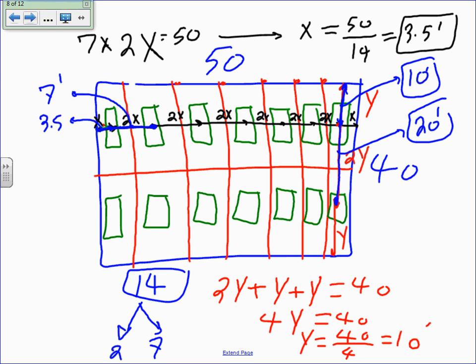So most likely, if I have a grid exactly like this, so 3.5, this is 4, I need a 3.5, so most likely my first fixture, because I can't, is going to be right in this area here. Okay, any question guys about this? Then what's the distance between the two fixture to fixture, center to center? 7. So I'm going to go 7 feet, center to center, and go to the fixture, 7 feet. Right now, the way these fixtures center to center, guys, is 4 feet plus 2, 8. They are 8 on center.